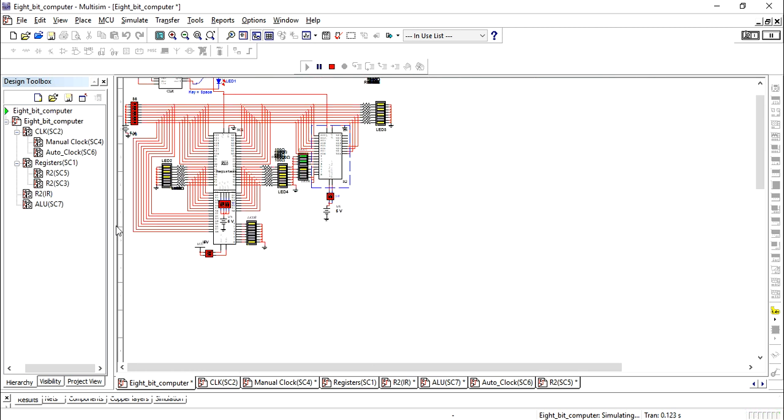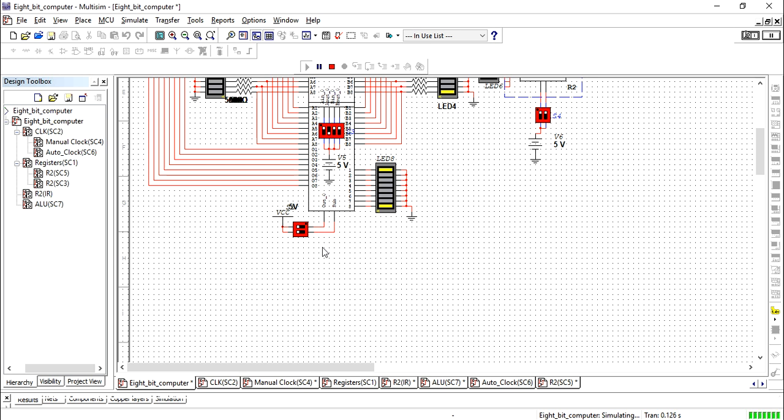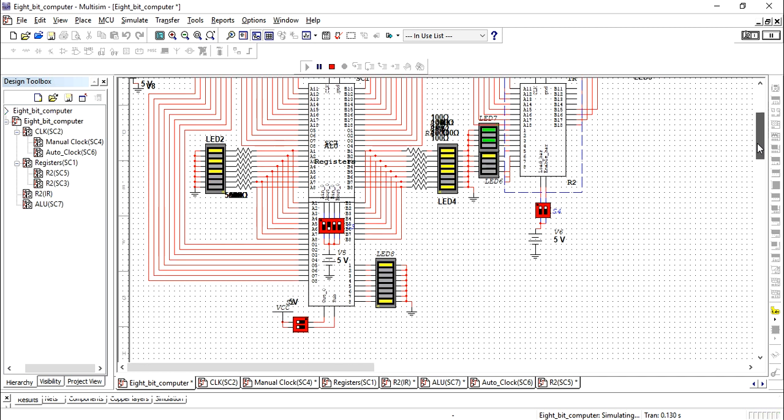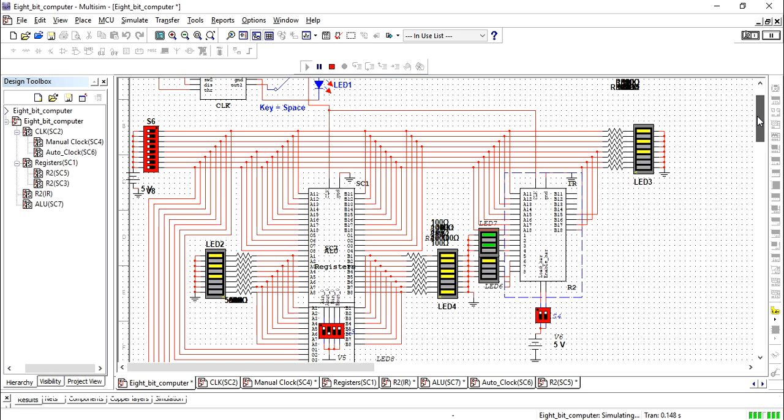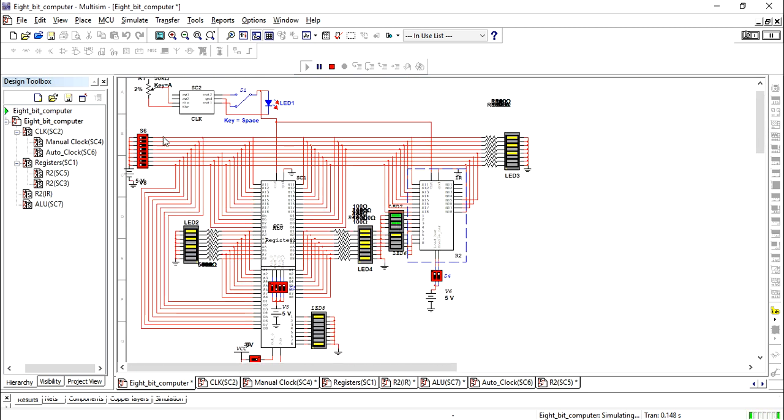Register A contains this one. Oh sorry, here the out bar signal is also enabled, so whatever is the output of this ALU is going to the bus. So I have to first disable this one. Now you can see, because the bus is only 8 bits, only one signal we can enable to send the data to the bus. So here I will enable this out bar signal, and I will enable this B in bar signal.